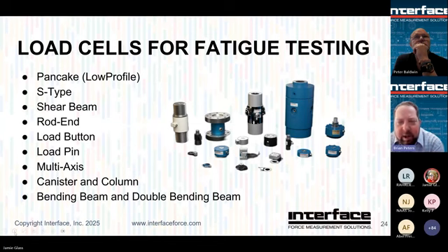So we make quite a few other flavors, but again, maybe you don't need 100 million fully reversed cycles. Most of our standard products are going to be good for at least 1 million, if not more, fully reversed. So 1 million fully reversed, which would translate to millions of cycles if used maybe only in compression or only in tension or not going to full scale every time. So again, just for reference, non-fatigue rated target there would be about 1 million without any concern. If you need to do a couple million with a non-fatigue rated load cell, talk with us and we'll get the capacity sized accordingly. So I keep saying that. What does that mean? Go to the next slide, please, Jamie.